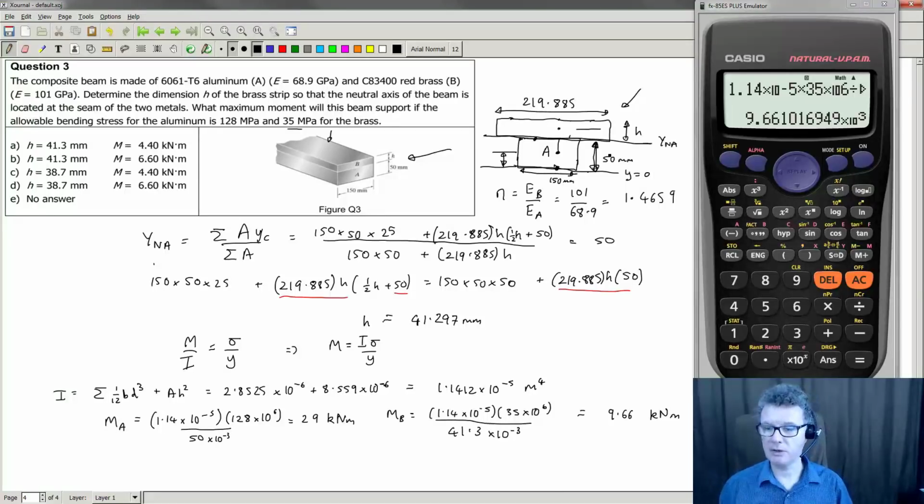that will have the effect of changing the stress, which will be based upon this N factor. So we're changing the material type. So you actually want to take this value and now divide it by the N, so that it's actually going to be the stress you would expect for the material when it's in brass. So you need to divide your answer by 1.4659.